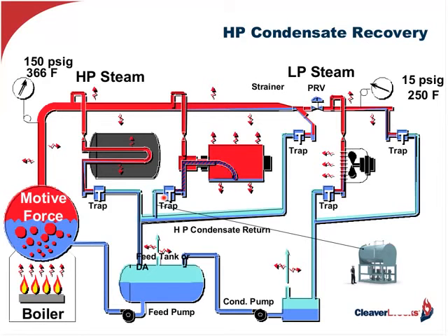Now, in many cases, this condensate line has not been properly sized for the biphase flow, and so what we'll do at this particular point is vent this flash steam off. This condensate will vent off some of that latent energy, get rid of some of that biphase, return it to a liquid so we can return it back to our feed system. So we flash that off through a pipe, and you'll see those plumes of steam, or condensate actually, coming out of those vents on the top of those roofs. That's what we're doing, so we can get the condensate back to our receiver.